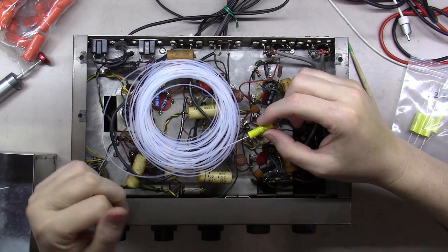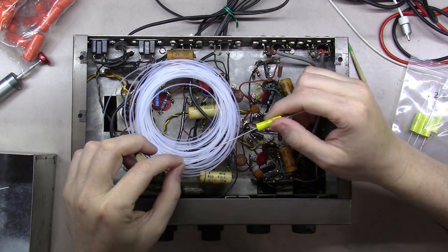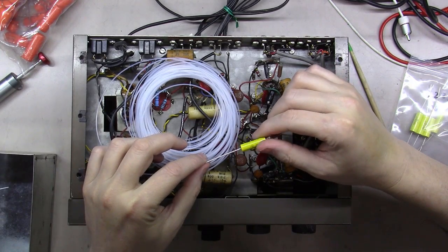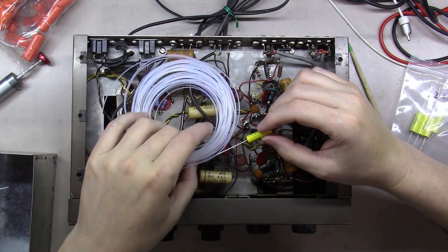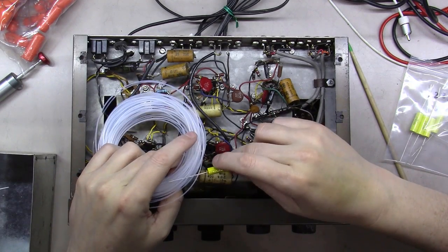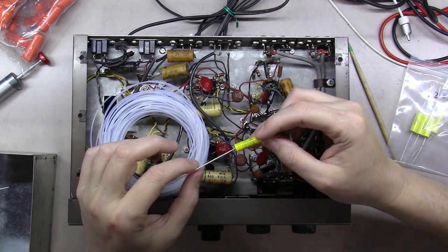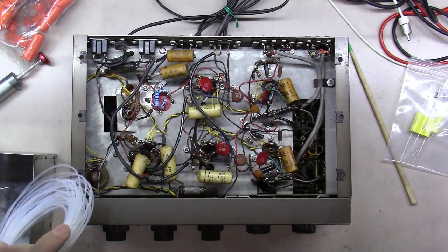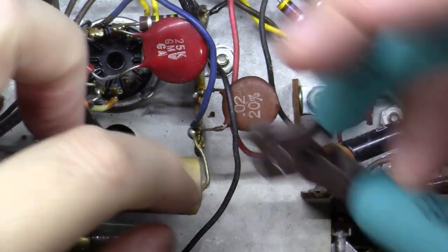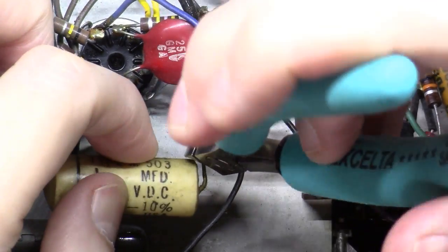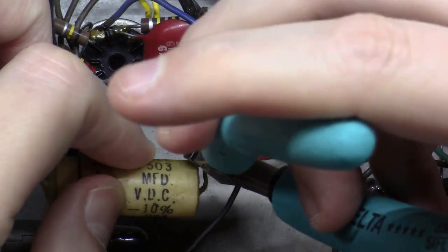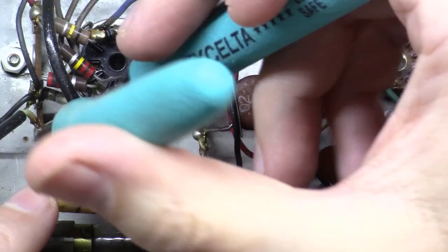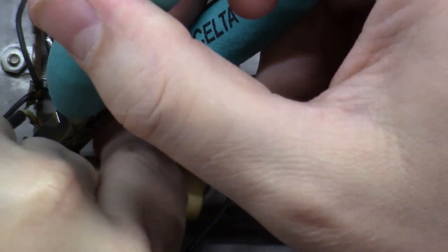All right, I do like to use PTFE wire cover here, and you can see I've slid it onto the lead of this capacitor. So as we're dressing from the capacitor down to where we're going to solder it, I like to use this to insulate the wires along the way. The way I like to do these is one at a time, and I like to just snip them out from wherever they're in the circuit. And pay close attention to where you snip it from, because you're going to have to put it right back.